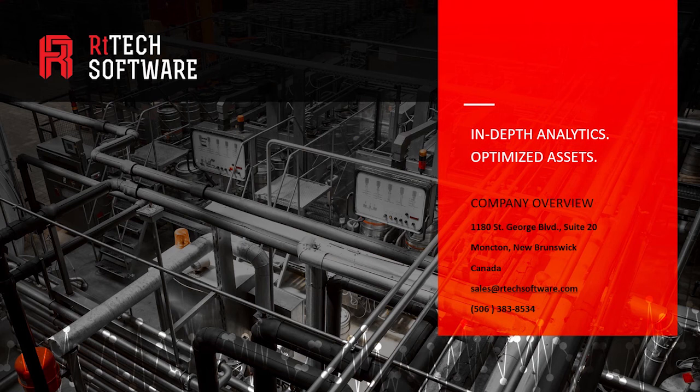So DUET is just watching that tag continually. As soon as that tag goes below the threshold, DUET will see it, and because Pi records very accurately when it went down, DUET just uses that timestamp recorded by Pi, watches the tag across the thresholds and generates the events accordingly. If it goes from one derate value to another, we cut the event and start a new event. So if we're down at 450 megawatts with a cold derate, and then we lose a feed pump and come down to 250 megawatts, RtDUET says that's a new event and asks for a new reason code, and that works very well for us.